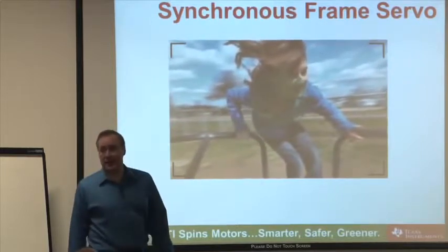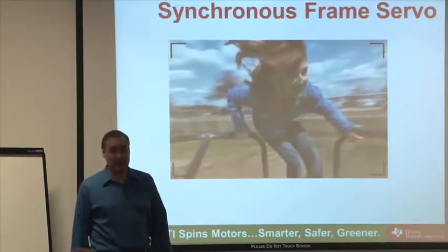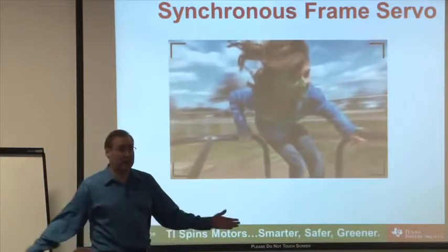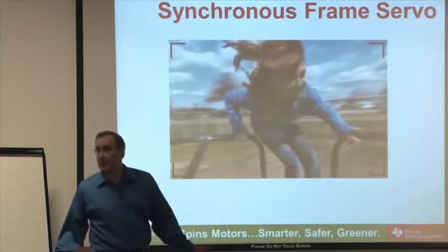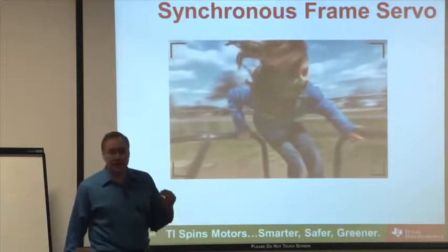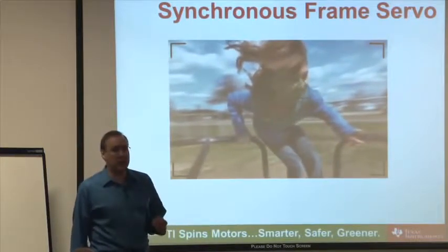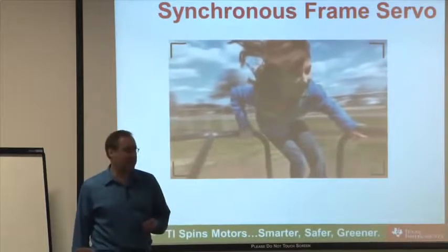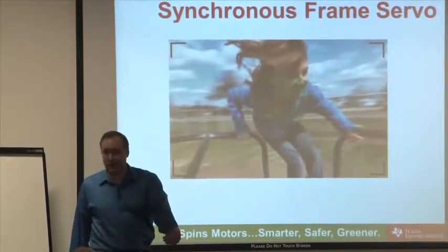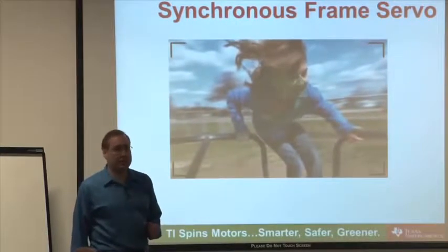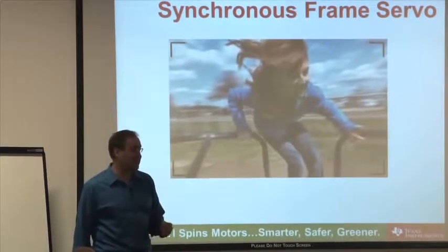It simplifies the dynamics of my system tremendously, and therefore I can get by with essentially just DC kind of regulators. That's the only frequency range I have to worry about now. Another way of saying it, and I've heard people say it this way, I've turned my AC motor into a DC motor. When you use field-oriented control and you jump up on the rotating reference frame, you turn your AC motor into a DC motor, is essentially what you're doing.